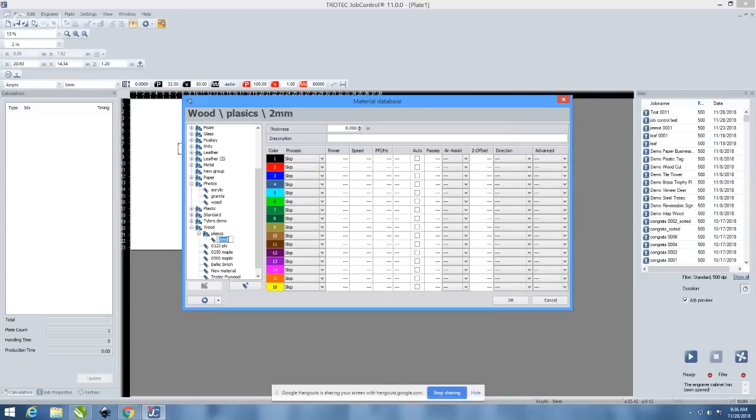And then you can save those settings, not just for materials, but even the settings that you want. For example, if you want to engrave a clear acrylic, you'd go out of focus. You can save that setting. If you want to engrave white on acrylic, it'll be in focus, so you can save that as a separate setting. This is why it's such an amazing tool to use within JobControl. The whole thing here is to streamline your working process. We want you to not think about anything: select it, and once it's set up, it's there. You'll never have to think about it again.